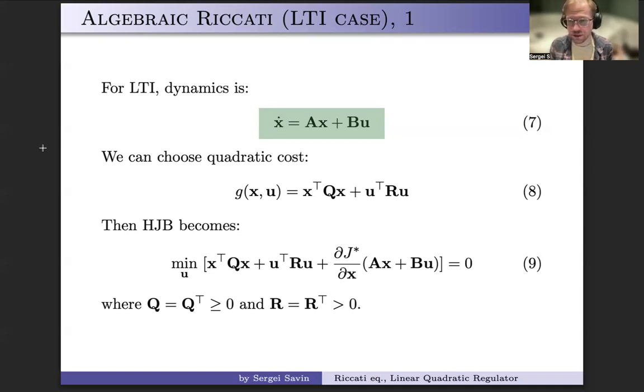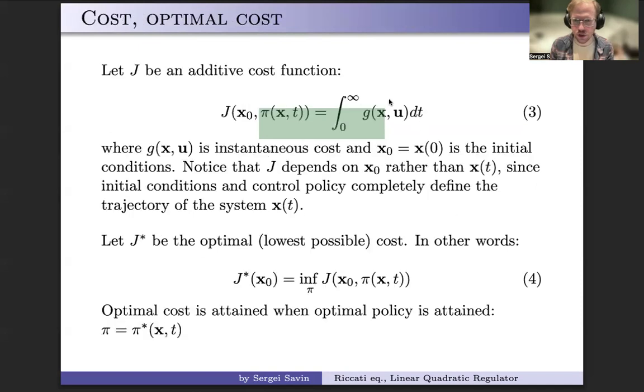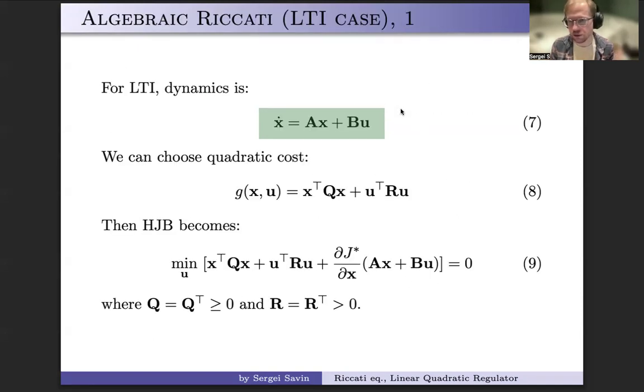The reason we don't have it is because we don't need it for LQR. This whole optimality formulation, as you noticed, is a function of state, not the output. We could try to formulate all of this in terms of output, but we didn't. So output is irrelevant for this formulation.